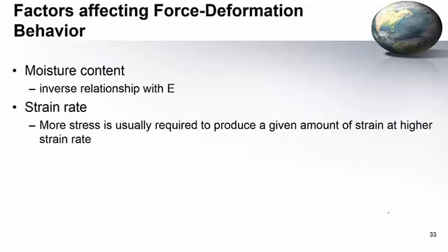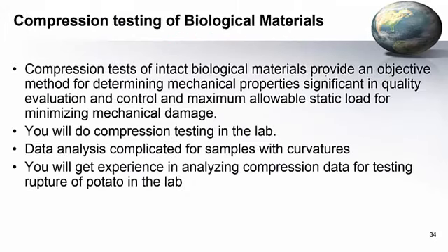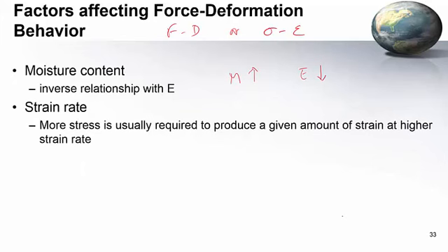The force-deformation behavior, or the FD behavior, or the stress-strain behavior, is related to moisture content, right? Typically the moisture content has an inverse relationship with the modulus of elasticity. The higher the moisture content, the lower the modulus of elasticity.